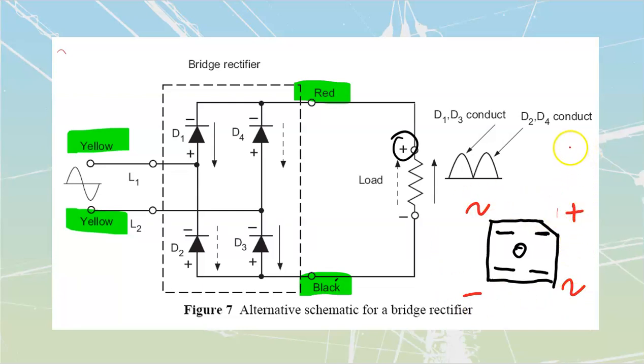The positive is going to be identified with a plus, a red dot, a clipped corner, let's put in CC for clipped corner, or it is going to have an out of alignment lead. That is going to tell us that it's the different one. You will be able to identify these things in the field. Most of these cases are going to be no more than about 1.5 inches by 1.5 inches. They're relatively small components that are just going to be screwed down into the back of the cabinet, and we just tie our leads off to these things.